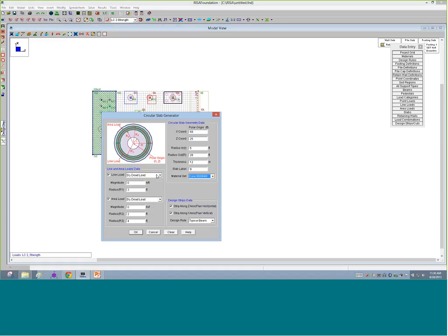What's also really powerful in this is I can set up some loading. So I can do some line loading in this. The first option here gives me, again, the ability to choose the category of the loading type. I'm going to tell the program it's going to be maybe 1 kip per running foot. And for the radius, I don't want to do 3 feet there. I want to get it onto my slab in my donut here, and I'm going to say it's going to be maybe 8 feet. If you remember, I have 5 feet in the inner hole. So I'm going to say the first radius for line loading is going to be 8 feet in.